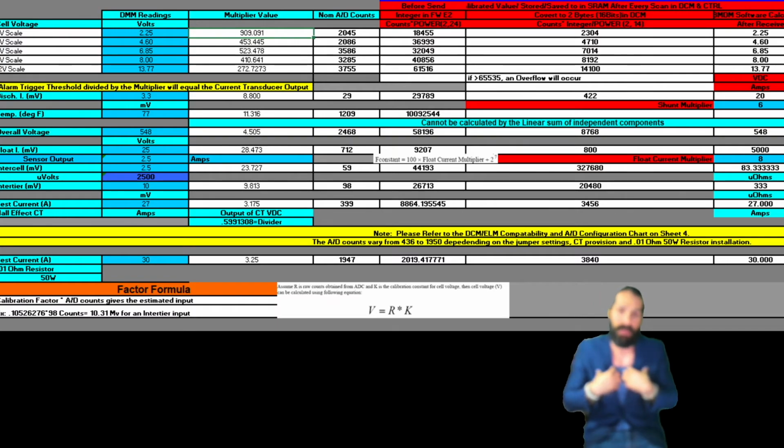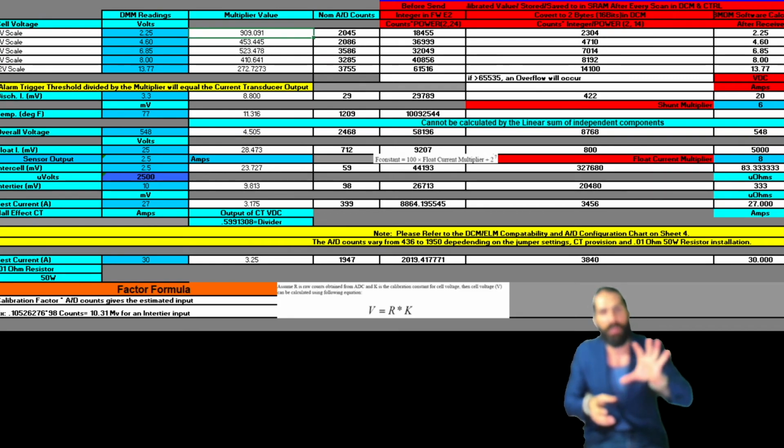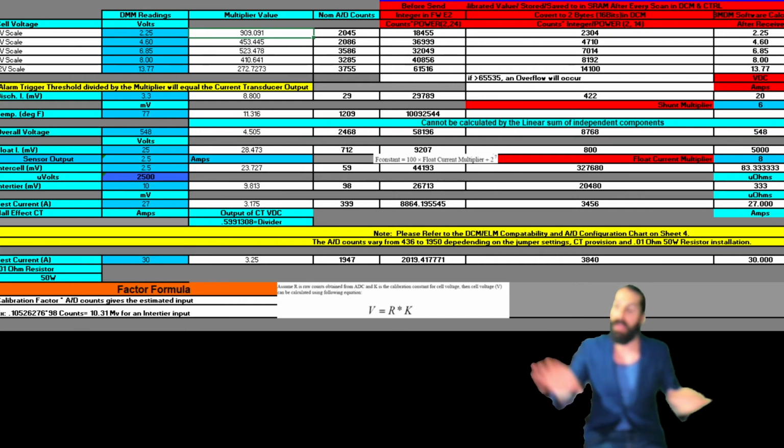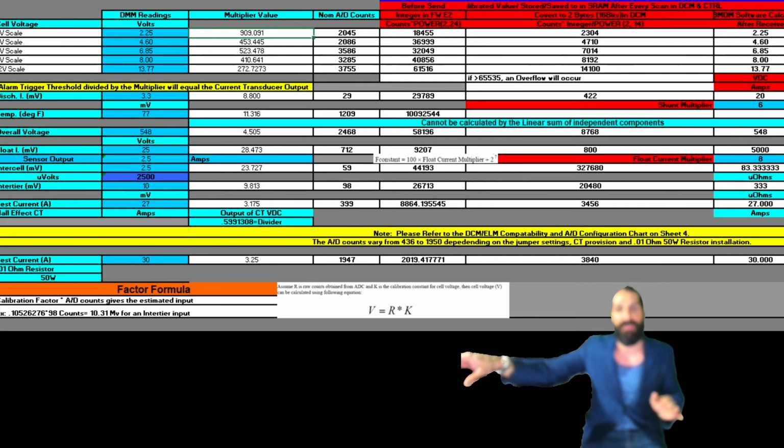And in my opinion, they should have monthly, quarterly, semi-annual, and annual inspections, calibrations, and verifications, because this system is essentially ensuring the heart, the core of your power system, that you don't have a 10, 20, 30, 40, $50 million outage. It's the core of your system that is ensuring you have enough critical load protection time for the generator, or your backup flywheels, or your diesel rotary UPS to spin up and protect your critical load within operational manufacturer specifications.